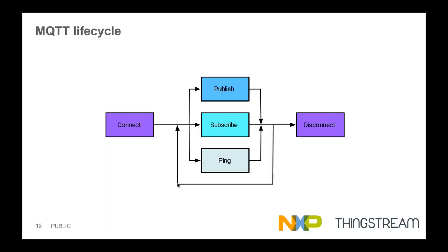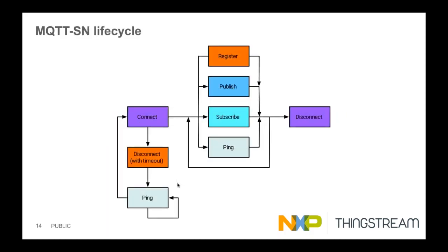Now, MQTT-SN adds some additional lifecycle components that are really useful when thinking about building disconnected and low power devices. So the chart here is similar in the center. If you start in this connect box on the left-hand side, you've got the same connect followed by publish, subscribe, and ping. But there's another option up here that's called register.